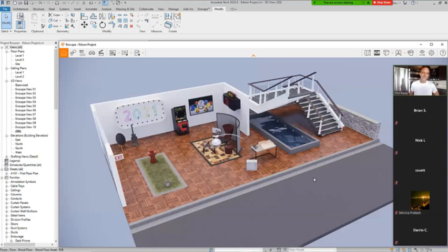So the thing about the animation tool is it is capable of enormous subtlety, not very fancy. You can't move the camera in every direction. You can roll the camera, you can turn the camera this way. You can change the pitch this way. You can't roll the camera that way. But aside from that, the camera tool in Enscape, the animation tool, is capable of really extraordinary subtlety.